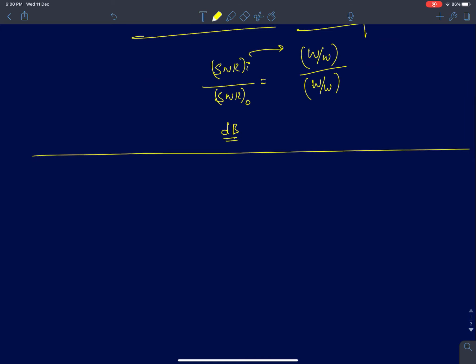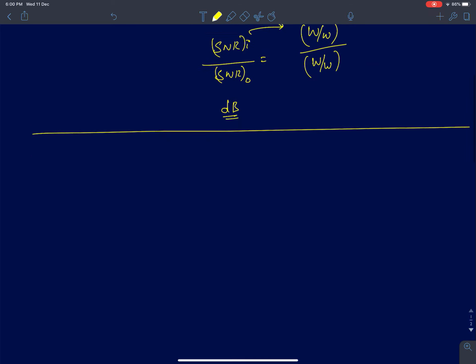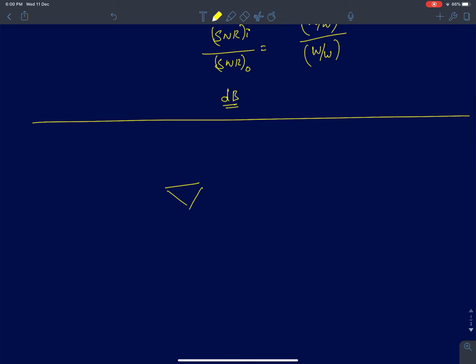Next, when we talk about a receiver, immediately following an antenna we have a band pass filter. Mainly the band pass filter is present to filter out interferers. In an RF system you have a signal and a strong interferer. Normally we want to filter out the interferer, so therefore we need the band pass filter.